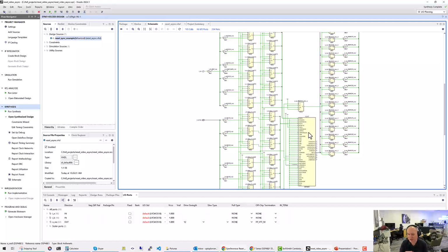What this means obviously is that we've got a lower performance because there's more routing delay in between the registers and the DSP48, which impacts our performance. It also impacts our utilization because we're using a lot more registers when we could be effectively using the ones within the DSP48. And that can also have some impacts on our power. So I guess the lesson from this little video is to really think about what you're going to do when you're writing your code and what you're mapping it to at the hardware level and where you intend it to go. And that will help you get a much better result.